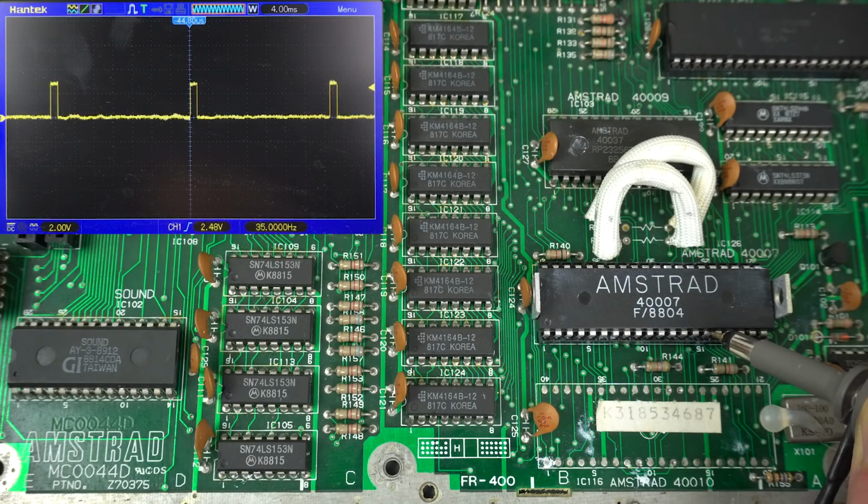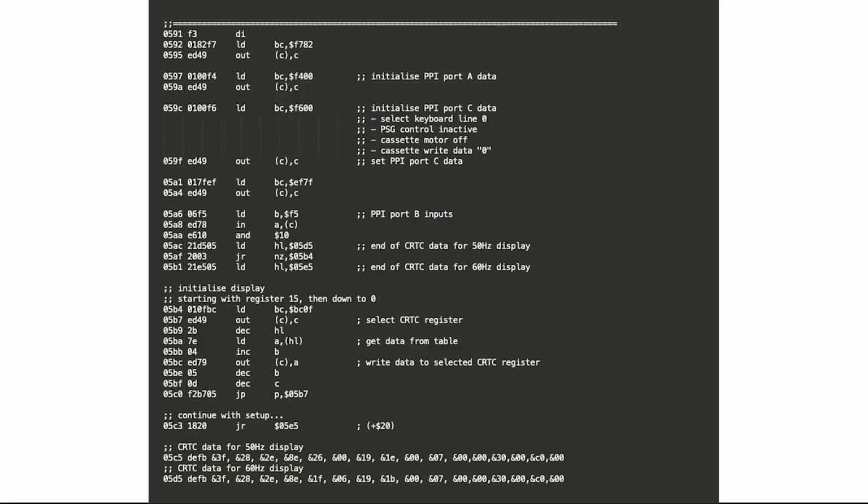Going back to our original question, how exactly is that setting the wrong frequencies in the CRT controller? I puzzled over this for a while, and the only good answer I came up with is if during the Z80's wild execution of code, it actually landed at address 05B4 without executing the code preceding it. That would load up the CRT controller with whatever data HL is currently pointing to. So I'm going to say that's the most likely place we're jumping to from somewhere and setting completely garbage CRT settings.